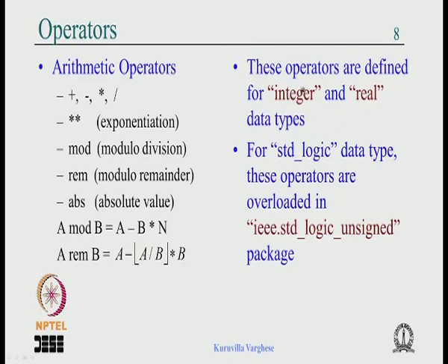These internal operators will not work for the standard logic data type, but if you use the standard logic unsigned package in the use clause, like you say library IEEE and you say use IEEE.std_logic_unsigned.all, then you can use plus, minus, multiplication, division and all that.